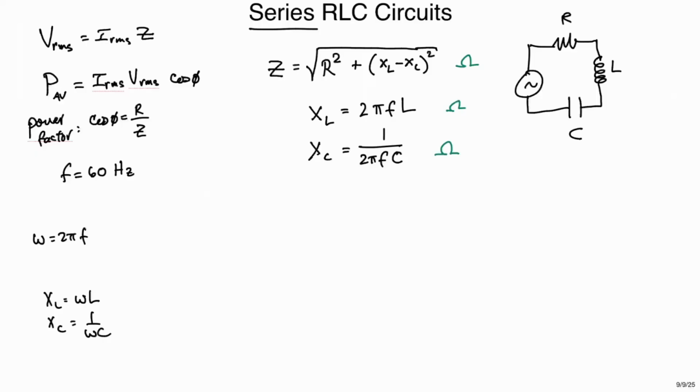All right, so what else do I need to warn you about before we get there? Oh, yeah. Another way to find the angle, it's called a phase angle in the circuit, is to take your reactances and subtract them from each other and divide by your resistance. So let's see here.